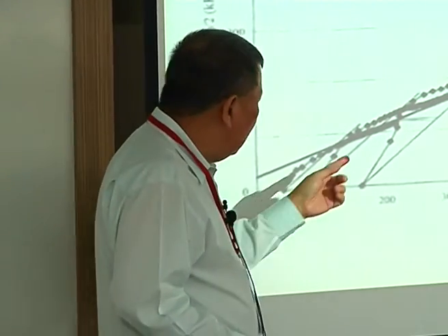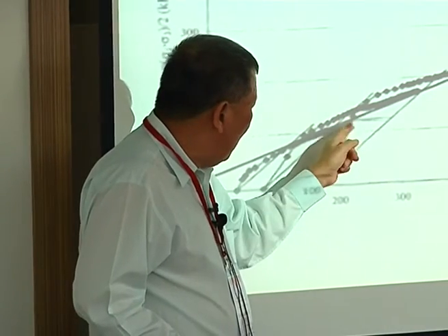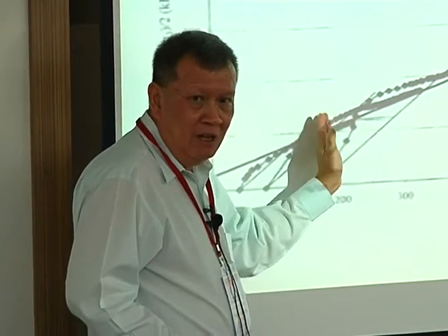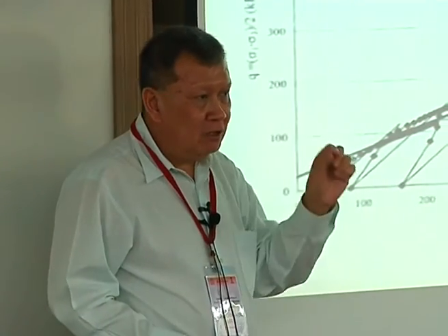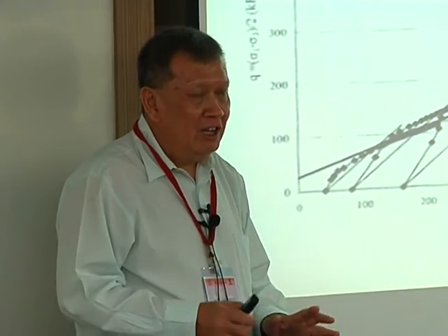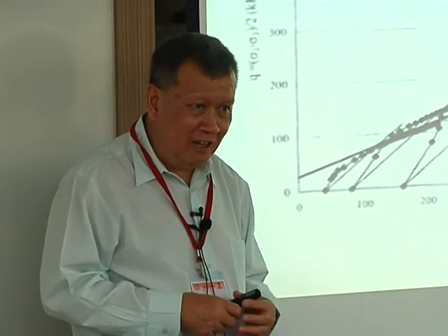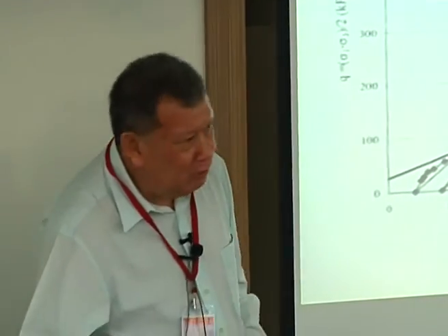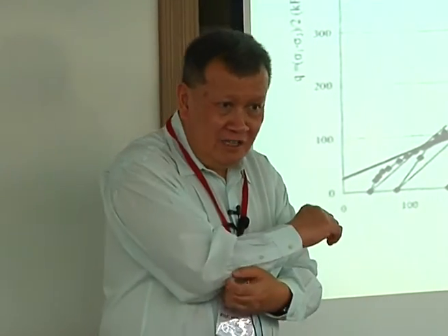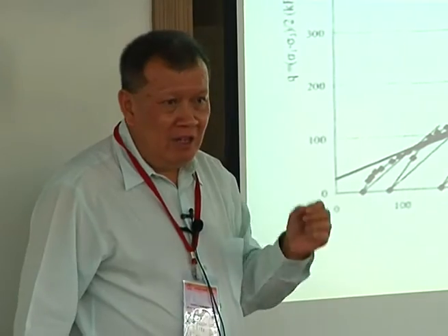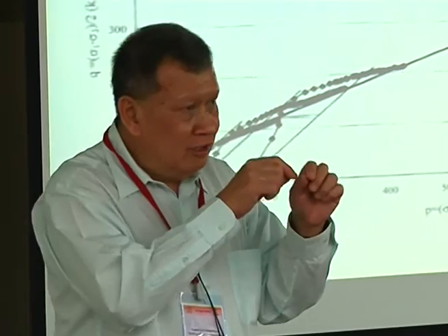So you can see the yielding is very clear. It is very nicely elastic up to around the line of failure, the failure envelope, and then it suddenly switches over. It just turned around. The reason is that yielding has occurred. The moment it yielded, the effective stress path is no longer 3 to 1. It's no longer linear elastic. So in fact, it's a very nice way to tell whether your failure envelope is correctly drawn in certain situations. It can be very, very sharp, much sharper typically than the stress-strain curve, drawing stress versus strain.